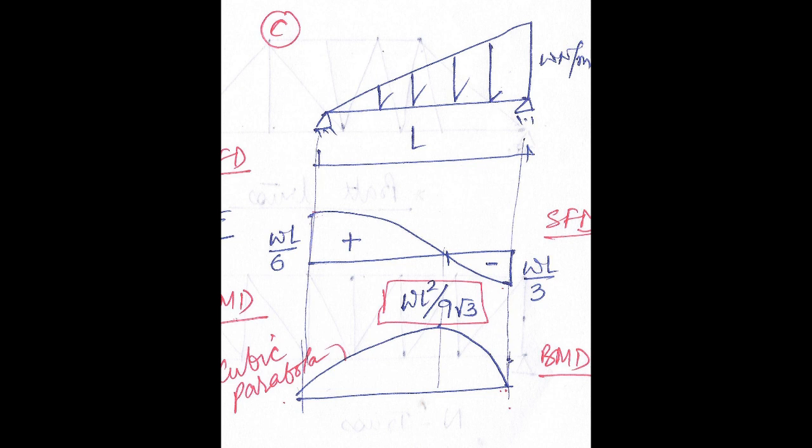So please remember this value, and also please note that in the previous case, in case of a UDL the BMD was a parabola, and in case of a triangular load the BMD is a cubic parabola.